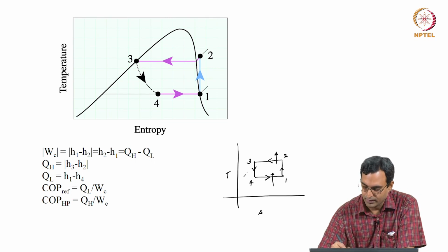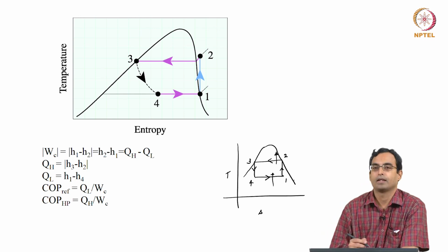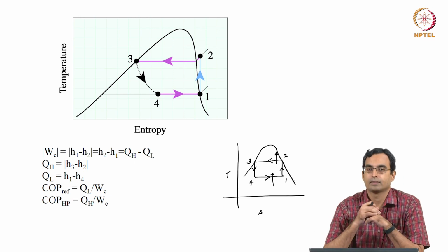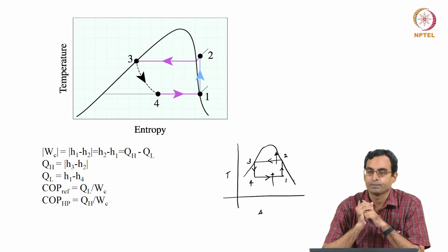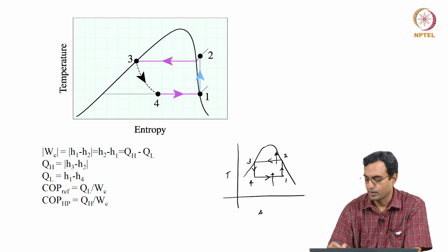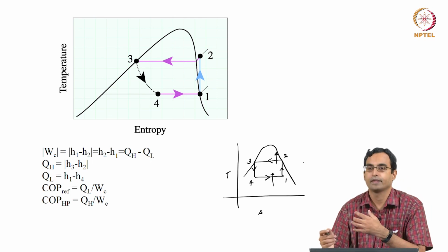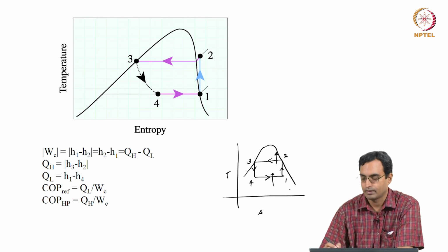to use two-phase flows. So that is essentially what we do, like in the other cases. We do this with a two-phase mixture, because then a constant pressure process is the same as a constant temperature process, and constant pressure processes are something which we can achieve. So this is a modification which we would first do. Instead of using a single phase substance, we could do this in a two-phase mixture and then run what would